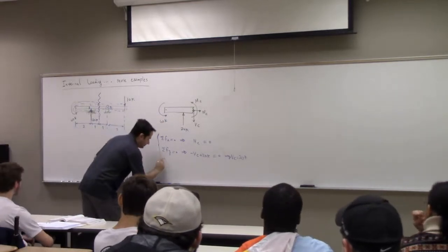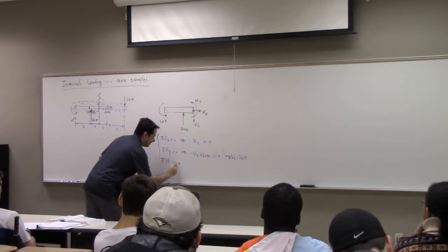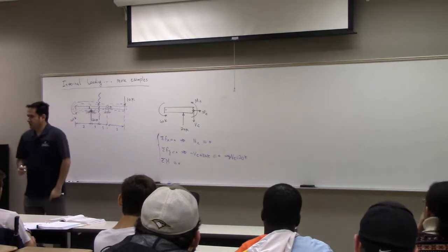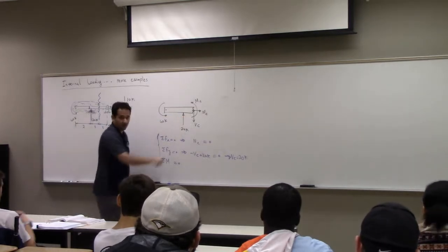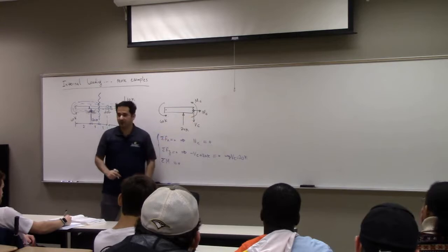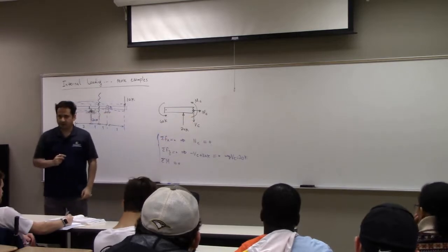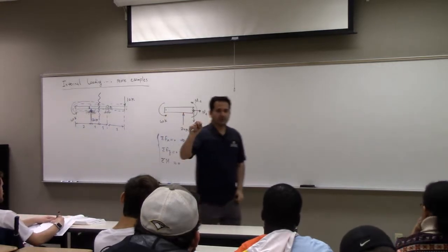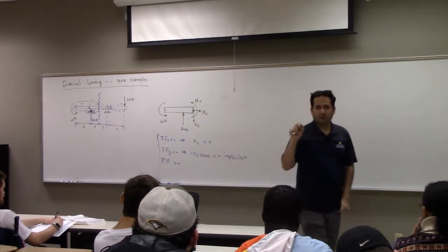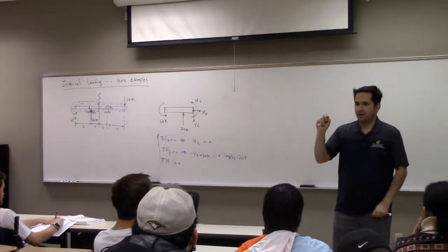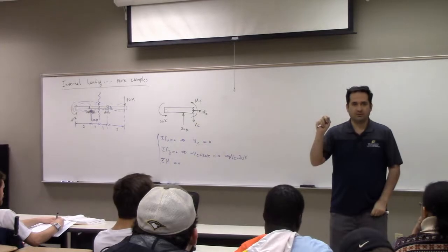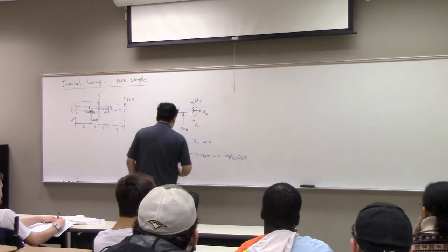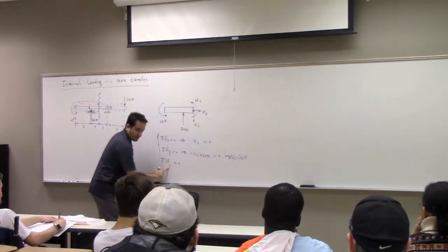So now I write my last equation, summation of moment about any point is equal to 0. If I want to find MC, what would be my best choice? Around point C, because I can eliminate NC and VC simultaneously. You remember, it is another review in vector statics. When we choose the reference point for moment equation, the goal was to choose a point that you can eliminate as many unknowns as possible simultaneously, in one shot, right? In this case, C is your desired point, so I put sub C.